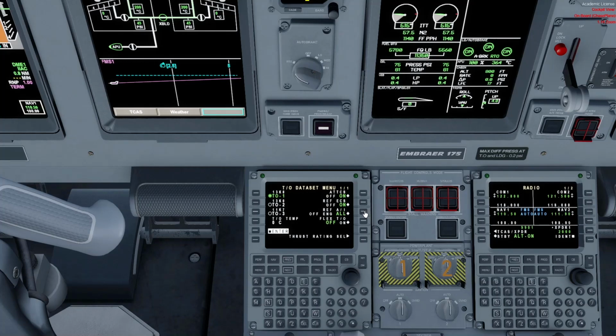with visible precipitation, we would use ref anti-ice all. Okay, and what it does is exactly what it says. It would turn the entire anti-ice, wing and engine anti-ice, on until 2 minutes after takeoff or 1,700 feet, at which point that logic is dropped and the logic of the ice detectors kicks in. And if at that point they detect ice, the anti-ice system will stay on. If it doesn't detect ice, it will simply go off.